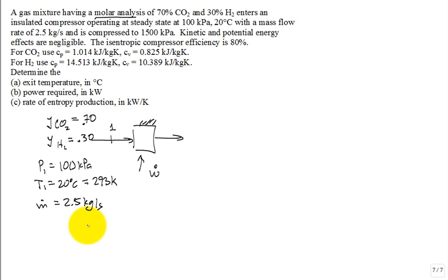All right? Is this mass flow rate the mass flow rate of the mixture, or of the CO2 in the mixture, or of the hydrogen in the mixture? Which is it? It's of the total mixture. Now, you're going to have to know the molar masses to switch back and forth between a molar description of the problem and a mass description of the problem. Let's continue to read the problem. A lot of students like to stay in the mass description if they can solve it that way, completely using masses. Or they'll switch with a little arm twisting after they get more familiar with the molar description.